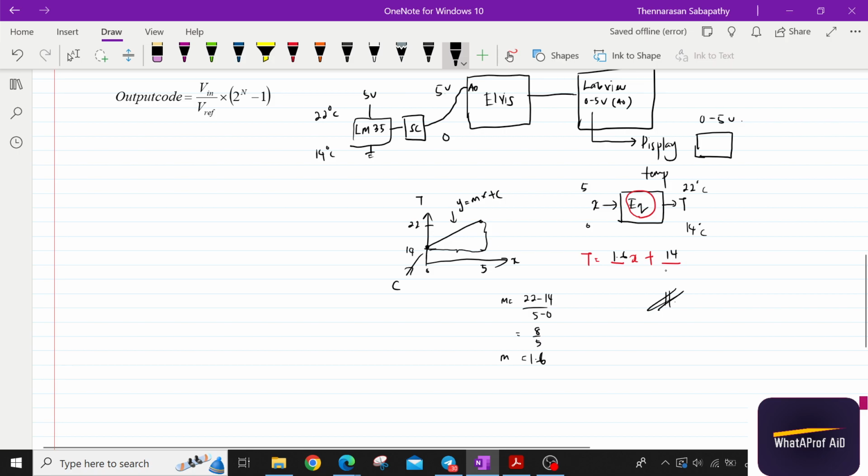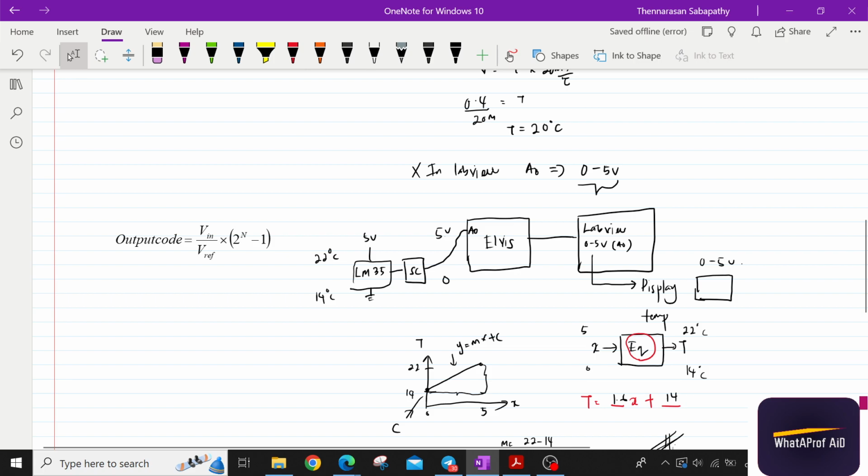Okay, then this is what happens with LabVIEW. Don't get confused later, because LabVIEW directly does the ADC by itself, and then the DAQ assistant will produce the 0 to 5. What voltage it actually measured will show here, unlike other microcontroller or microprocessor boards.